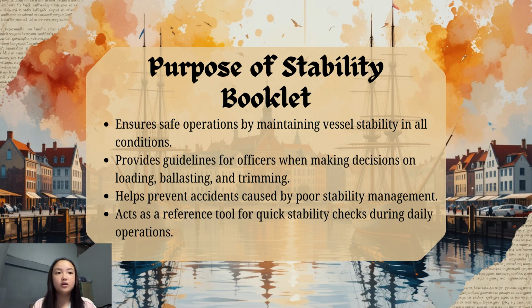And also, it guides officers in loading and ballasting. Second, it helps calculate draft, trim, GM, and GZ. Third, it keeps the ship compliant with IMO and class rules. Fourth, it provides instructions for emergency stability. And the last is, it is used daily for sailing and during voyages.